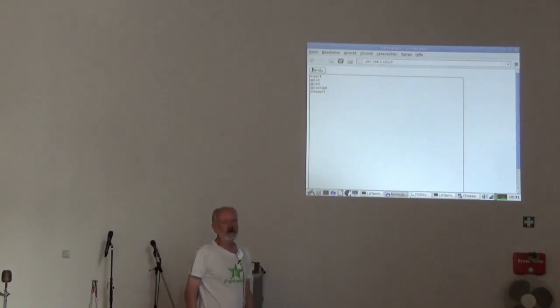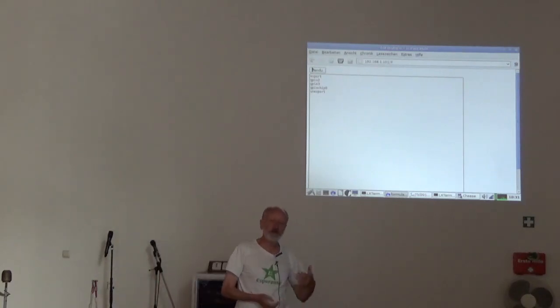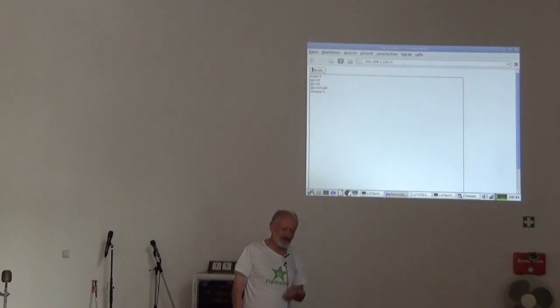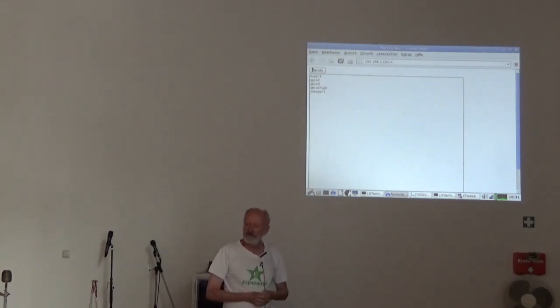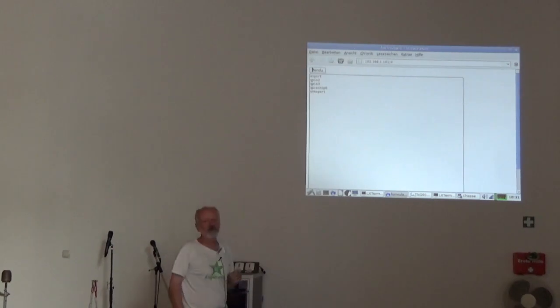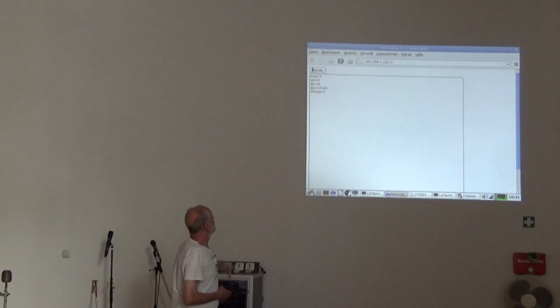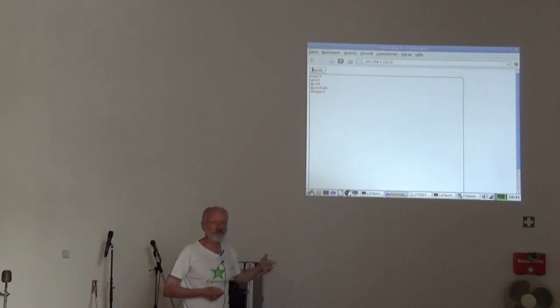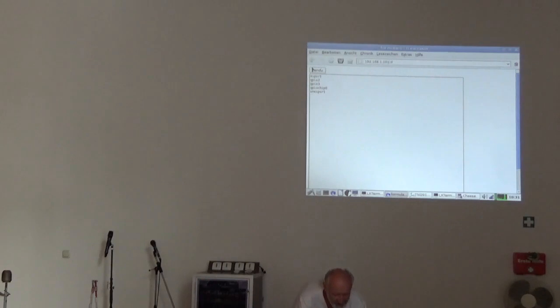And as an answer, this script starting I2C gives back the content of the directory. Now you see normally when there are no lines exported, we don't have these GPIO 2 and 3, so now they are active. And the next thing is I have to start the server, and I load the script server 8888.